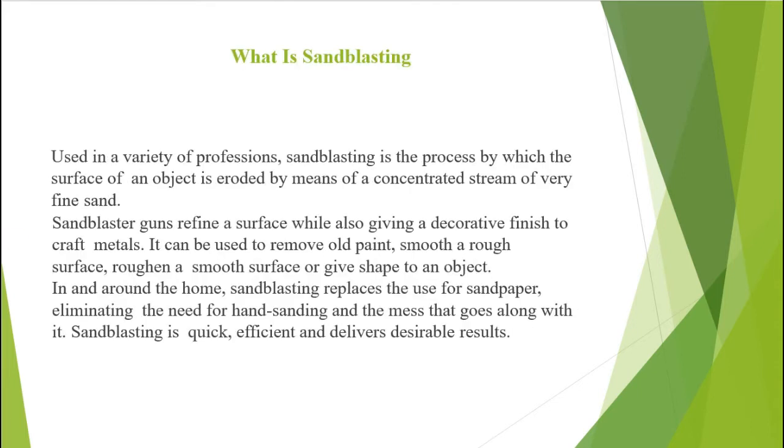Now, what is sandblasting? Used in a variety of professions. Sandblasting is the process by which the surface of an object is eroded by means of a concentrated stream of very fine sand. The sandblasting gun refines the surface while also giving a decorative finish to craft metals.